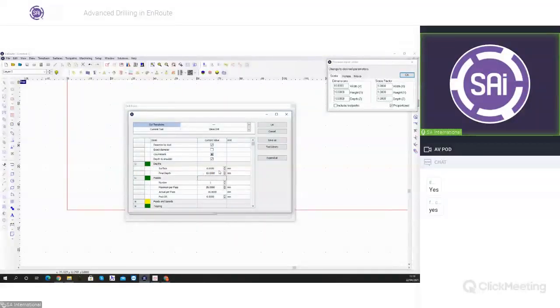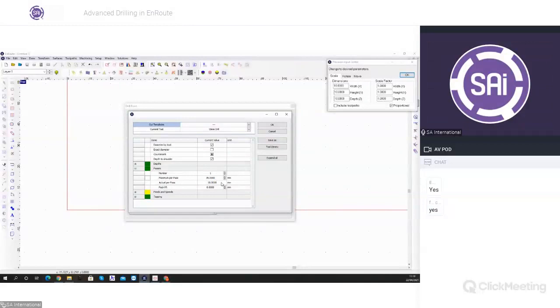Of course, here you simply can set your depths. In the passes tab here, of course, you'll have your maximum per pass defined by your tool, an actual per pass that you can see. If we change this value here, it will modify the depth of material that's routed away per pass.